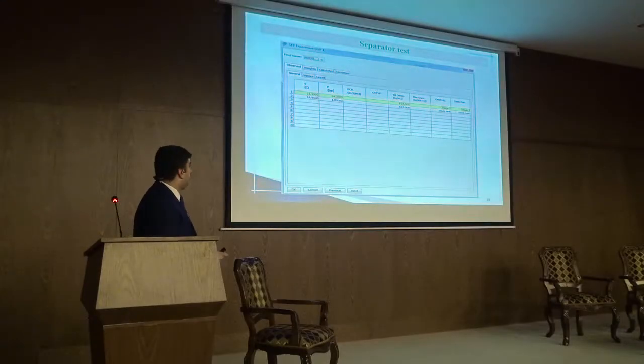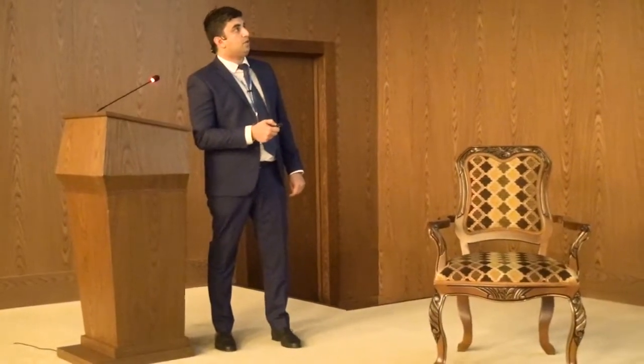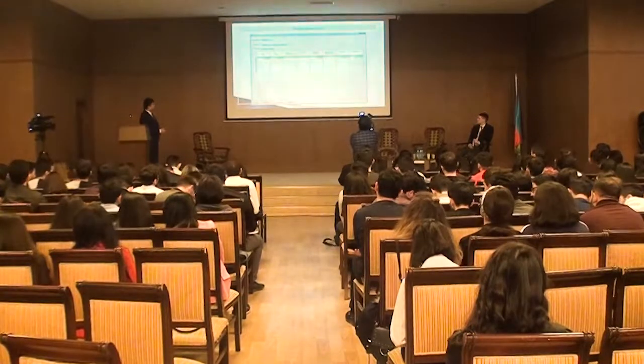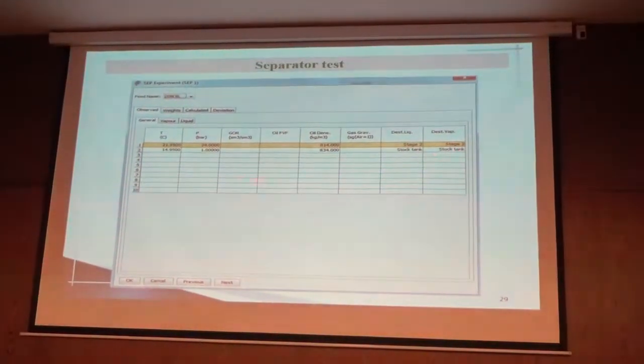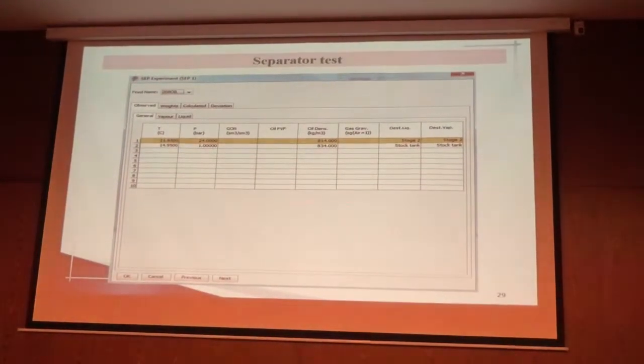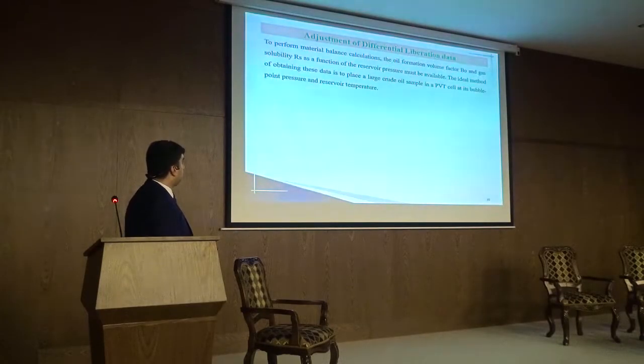And the separator test. Why is the separator test very important? As you see here, it is this temperature, these pressure values, all densities and values, and second stage separators and stock tank. Why do we need separator tests? Because we need to adjust the oil formation volume factor and gas oil ratio, which we get from differential liberation expansion tests.